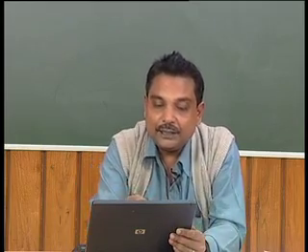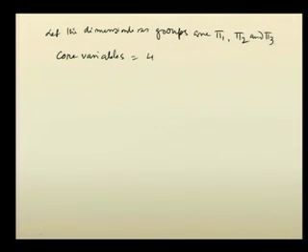So, core variables will be 4, and for the present case we will take d, k, mu and v as core variables. That means these core variables will appear in all the expressions of the dimensionless groups. We will see one by one.